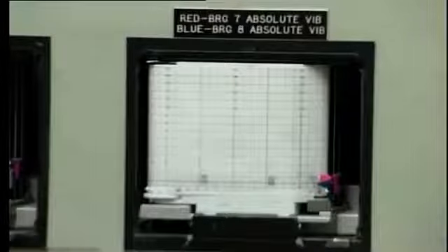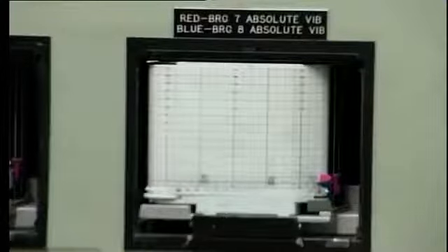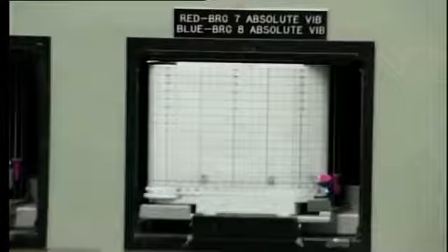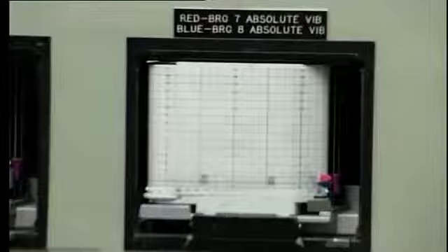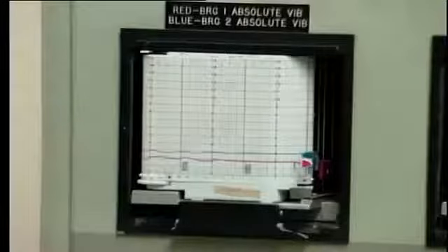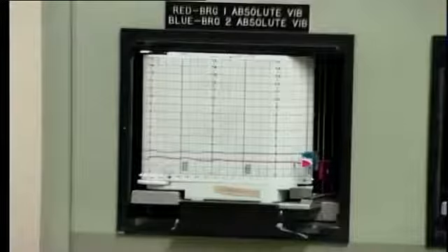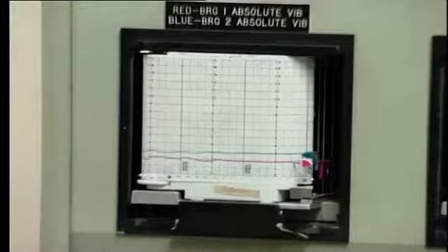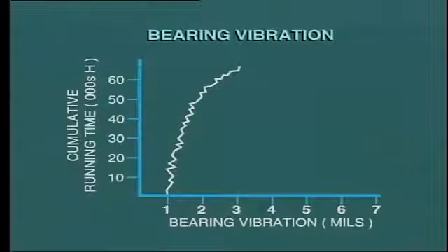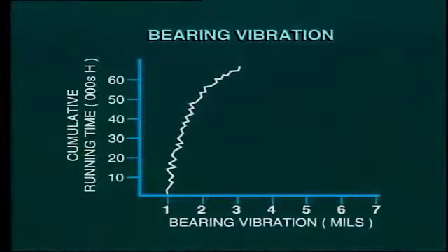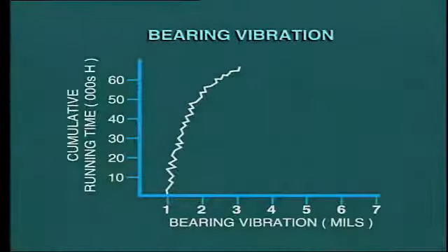For example, increased vibration on a generator bearing at a certain loading has been used to identify problems with the generator windings. Similarly, a temporary increase in turbine bearing vibration may be an indication that the operator is applying load too fast. If the magnitude of vibration on all turbine bearings steadily increases with time, it is probably an indication of wear and tear on mechanical components as the machine approaches the next overhaul period, usually every 5 years.